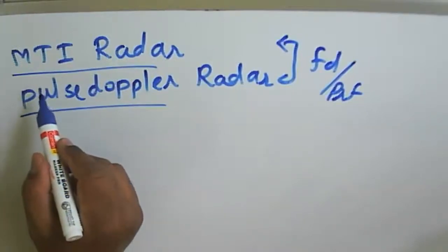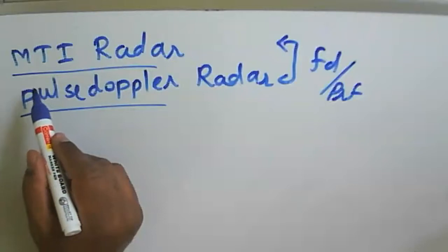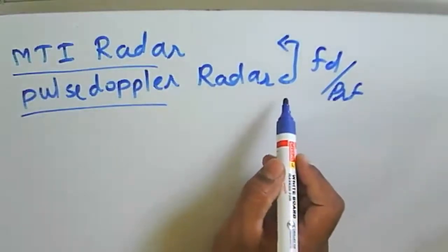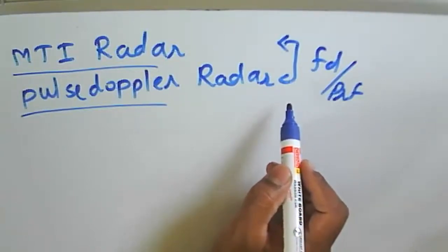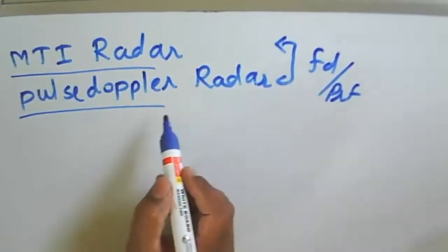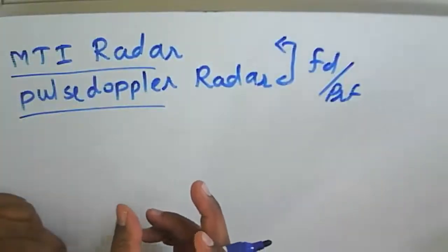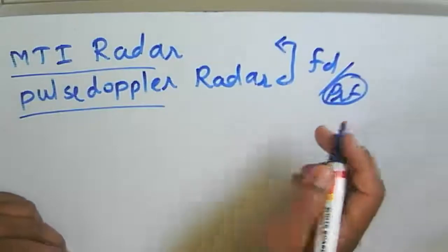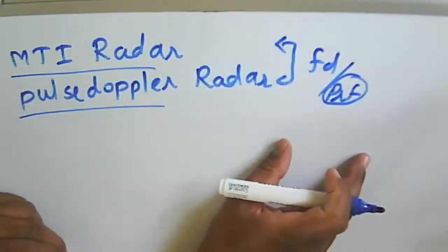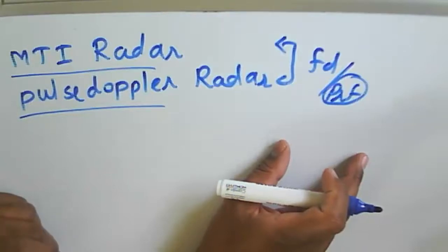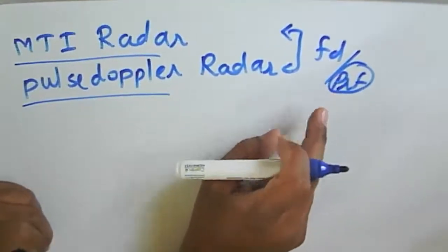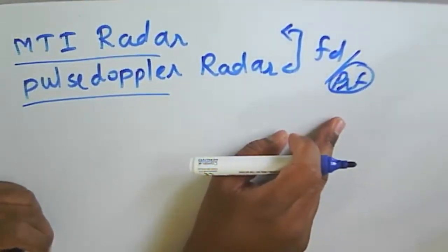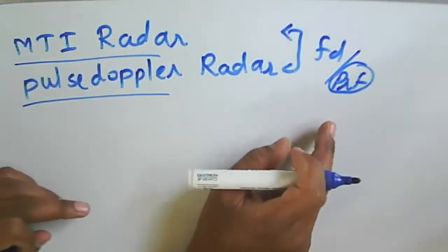In a moving target indicator, we are supposed to choose a PRF in such a way that no range ambiguities occur. But there are other issues present in MTI radar due to the given PRF value. There will be Doppler ambiguities, or at given pulse repetition frequencies there will be blind speeds.